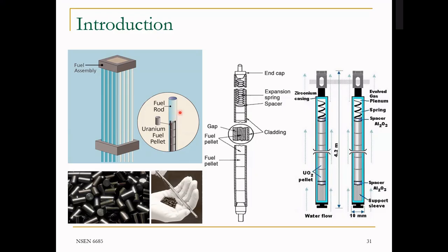That's a kind of an accident scenario that we don't like to have. It's called fuel cladding mechanical interaction. That could lead to a failure, but we leave a gap between the fuel pellets and the cladding. So see, that's a cladding, fuel pellet, and there is a gap. And this gap in the old designs in the light water reactors is filled with helium to just be sure that we are keeping that separation.